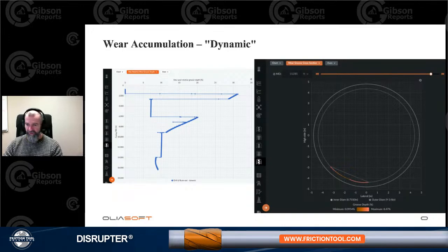Let's look at the other point that we looked at earlier, the one that was close to the end of the liner. And here we see a dramatic change. What we had before was one groove at about 10%. Now we have a maximum groove here of 8.5. And there seem to be a lot of other grooves located on the left-hand side there.